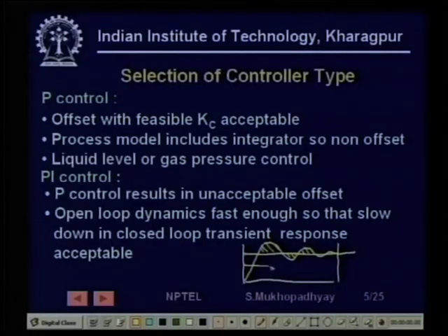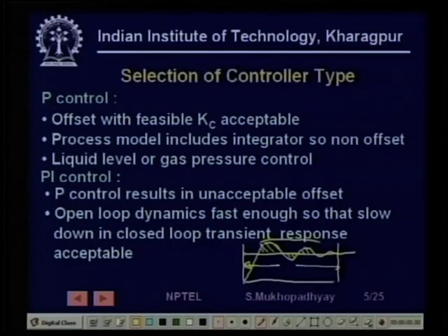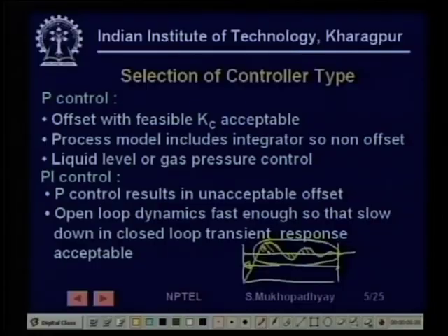So, if this interval over which there is some error is small compared to the frequency of set point changes, then you can say that okay, even if during this period I have some error and my control performance is maybe affected, depending on whether I have an integral error criterion, then it will be less affected, because this positive error is going to cancel this negative error. But even then I am able to tolerate this much error, because it is going to die down reasonably fast, and then it will stay on for a long time.